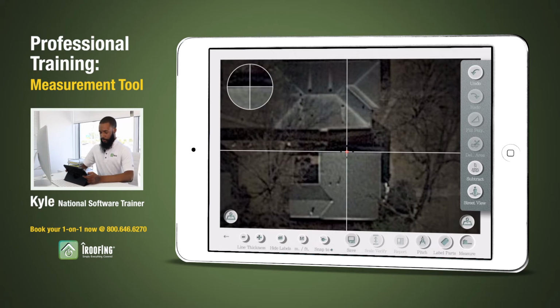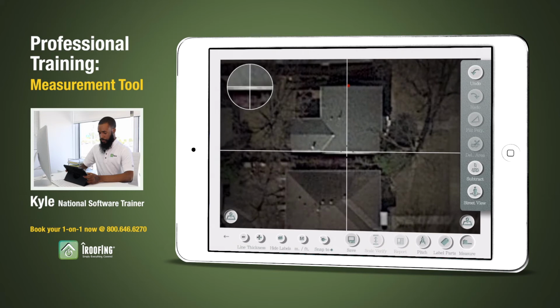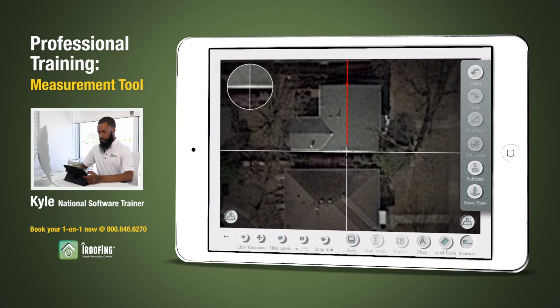From here, we'll work our way down this ridge until we get to the rakes on the opposite side. And I want the line that's above my crosshair to remain highlighted red, which lets me know that I'm aligned with my point on the other end of this ridge. Then I'll hit the marker button here to place down my next dot. And now I should have a line between these 2 points with the measurement for that ridge.